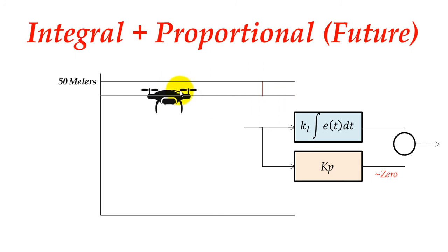Imagine this case where we have a very small error, in which we can consider the proportional controller is not working because we have an error which is very small and reaches 0. So we have no control action from this proportional controller. But actually what we have here is the integral controller will keep summing the error over time, so that we will find that we are not stopping at 100 RPM speed. We will pass this speed to another speed, for example 102. So what we have here is an overshoot, or we have reached an undesired value.